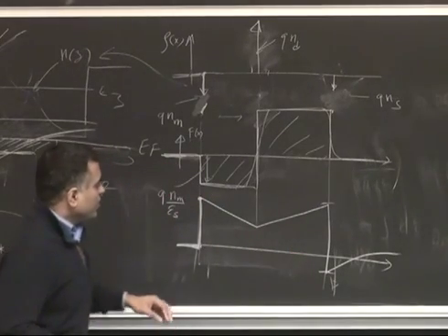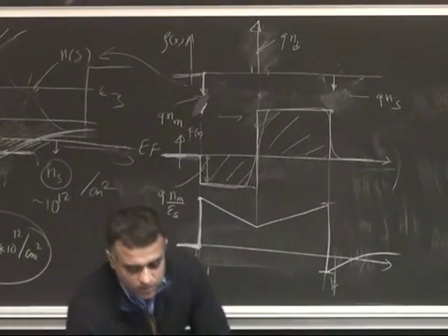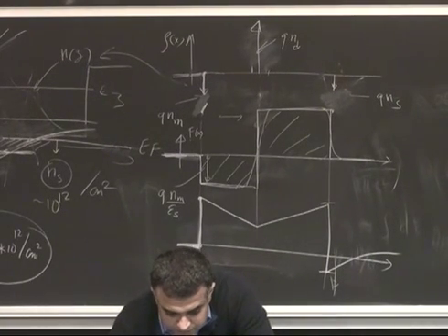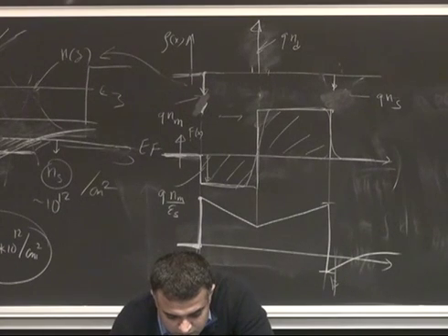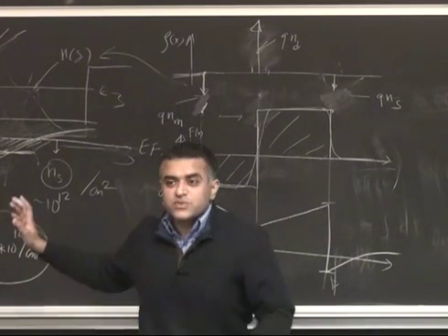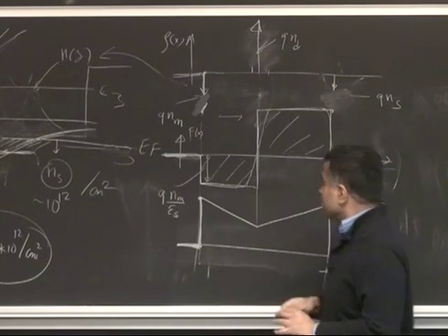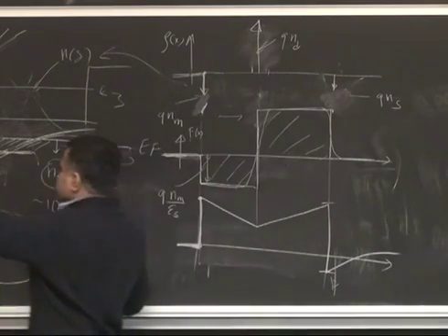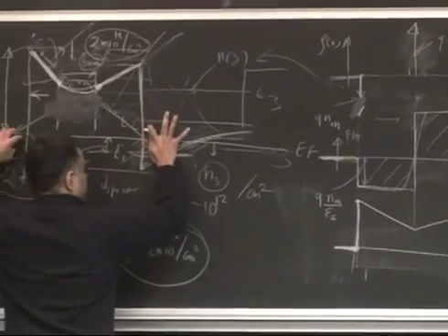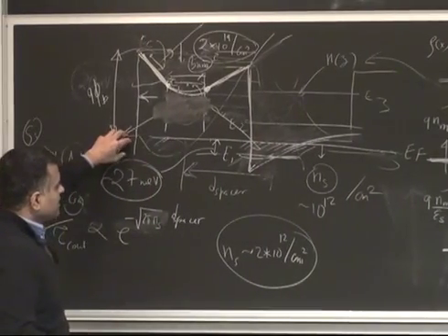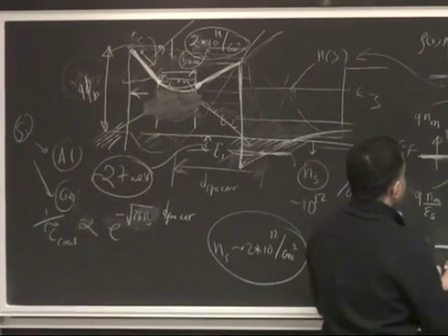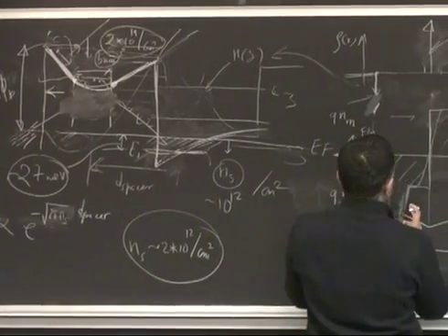Okay, so what I want to ask now is how does this charge depend on... any questions about this, by the way? We're going to look at this in some detail because one of the most important things about this device is, for example, what is the threshold voltage when I apply voltage on the metal and I have an electron gas of 2e12 sheet density sitting here and I change the gate voltage. Let's look at it this way. I think the charge figure is one of the best ways to look at it.